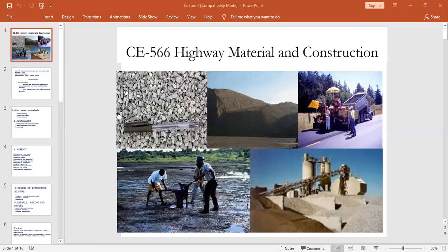In this modern world, we also use admixtures in asphalt concrete, but the form is different. We use actually polymer modifier in asphalt concrete. Some people use rubber modifier in asphalt concrete. So even though they are not admixtures, they are modifiers that actually enhance the property of the asphalt itself, and consequently, once the property of asphalt is enhanced, the whole mixture will also be enhanced.